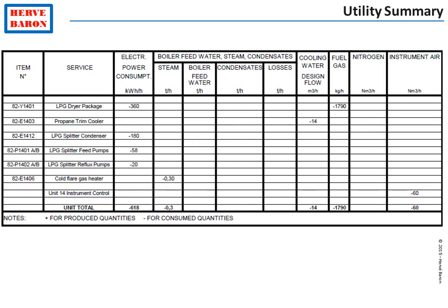steam, and so on. The total consumption of each utility serves as the basis for the design of the corresponding utility generation unit. You remember that utility units are designed after process units. Indeed, process units have certain requirements in terms of utilities, and only once these consumptions of utilities are known can the utility unit's design basis be established.